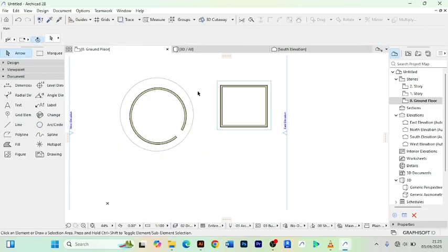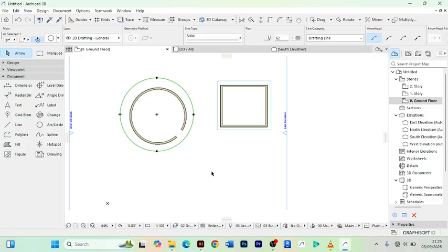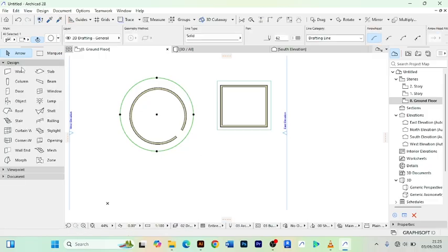Now this one has created a line. You select the line, then you come to your design, you select the slab, and you click on your space bar on the keyboard. You see it will turn the line to blue, and the cursor will turn into like a paint brush. When you click that, it will just pour a slab or a concrete into the line that you have selected.